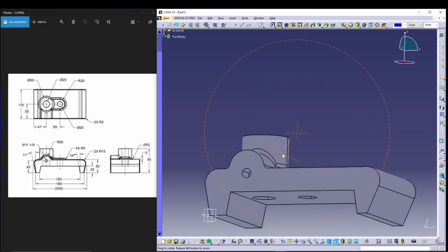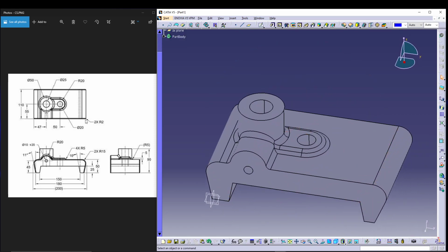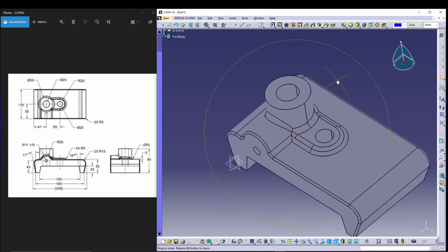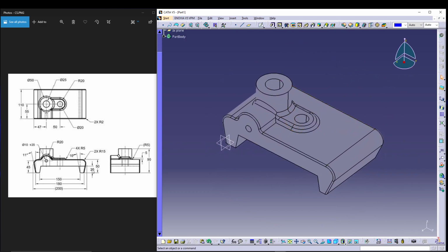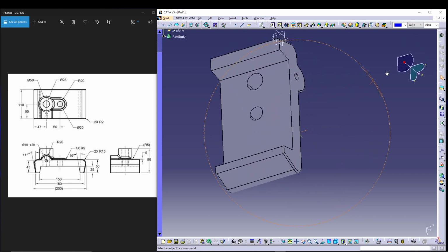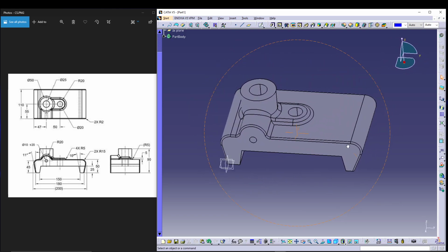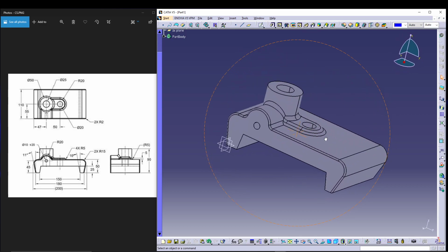Okay, and the other fillet is for these corners of 2 mm. So let's go for another fillet, this time 2 mm, and select this edge and this edge. Go for preview. Okay. So yeah, that wraps up our model of clamp stop. This one is very easy and nothing complicated, right? It's according to the dimension that we have, and that makes our model complete.